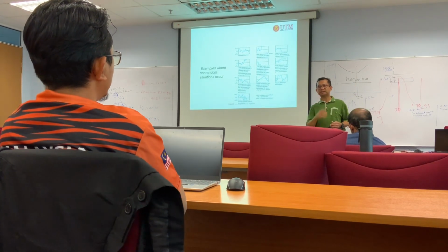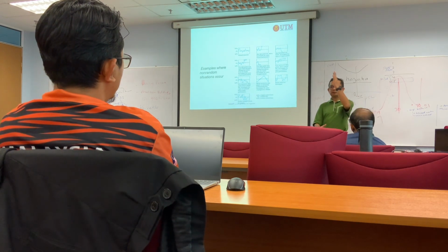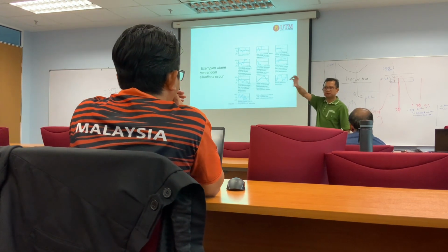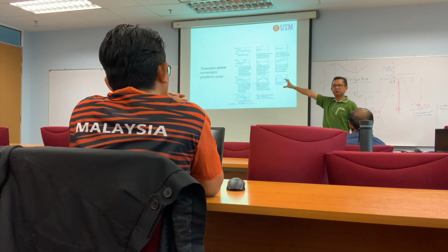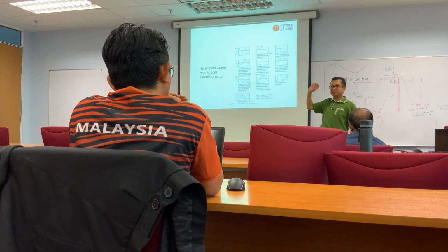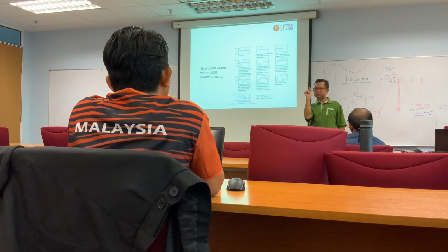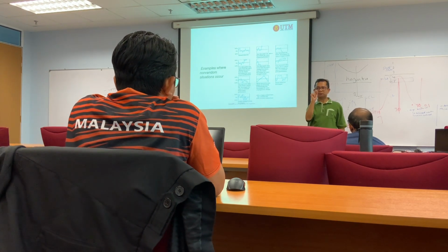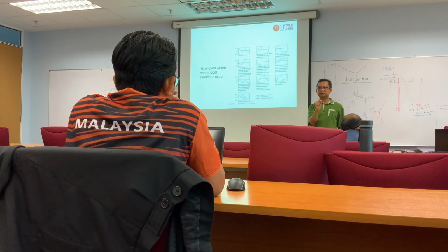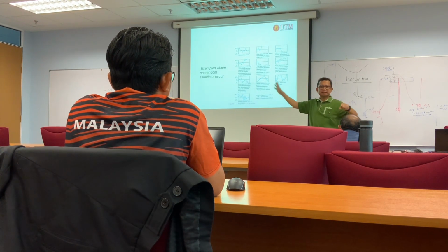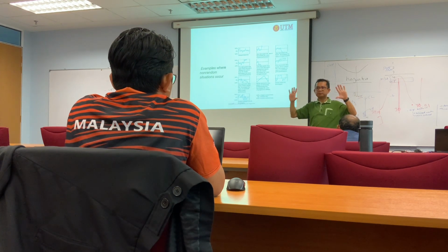So to answer your question about the company, whether or not we just base on what you got, whether it is close to the target or not, without plotting the SPC for the entire week or month, my suggestion is better you plot it because you want to see the trend, you want to see the behavior. If you just base on one dot or the average of one day average concrete, okay, it is here, so it's still beyond the limit. Without having the trend data like this, you cannot see your actual performance.